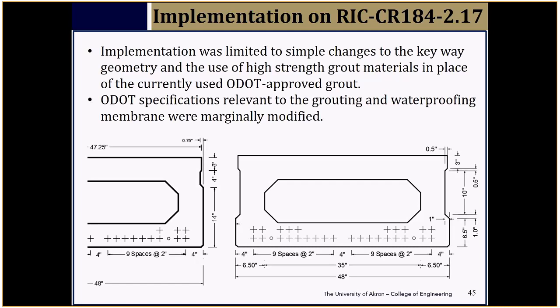And then number four, the opening itself is so small that we are not filling the joint adequately, or we don't know if we are filling the joint adequately if the opening is very narrow. If we increase the width, we are increasing the possibility of filling the joint adequately, number one, and consolidating the concrete after placement, which is very, very important.